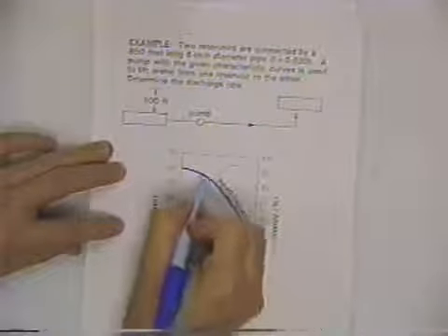Well, when you think in terms of pumps and their capabilities, there's a relationship, again, between head and discharge. If the pump has to work against a small head, it can pump a lot of water. But if you're asking the pump to lift the water some enormously great vertical distance, it's not going to be able to do so at a large discharge rate. And so what this curve says, and this would be given in the problem, because it's for a given pump. It's determined by the pump manufacturer. And it says for this given pump,